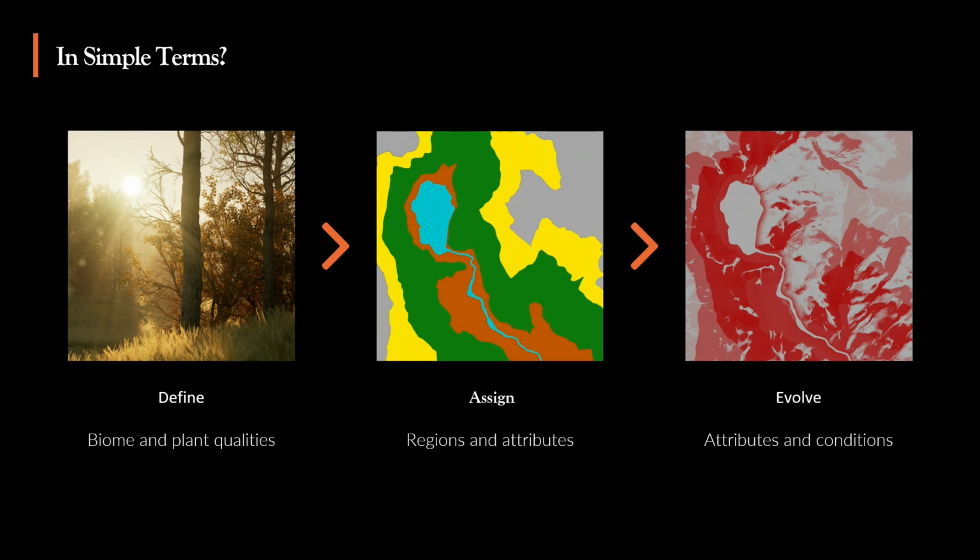Then once you have that, it gets piped in as a definition file. How we handle that is very flexible. In Houdini, those attributes are stored as geometry attributes, but for the user, we wanted to let the user be able to change it without opening Houdini. So the designers can use it, artists can use it. And also we wanted to make it extendable from the game engine side, so that if you want to write a custom Python panel in your game engine, issue a command or build your own interface that modifies those definitions, you can do that. That means the definition has a dual existence of geometry attribute and a JSON file. So the geometry attribute is optimized for running in Houdini, and the JSON file is optimized for you reading it.